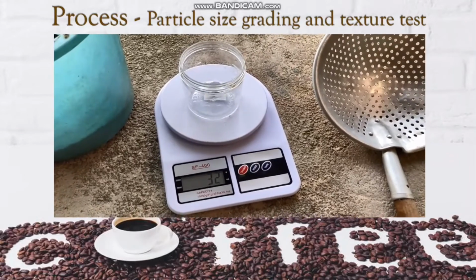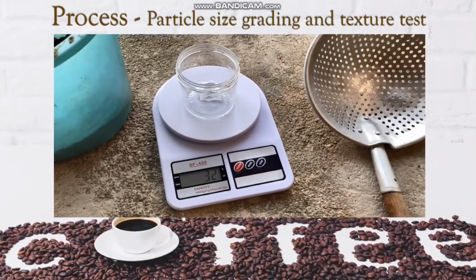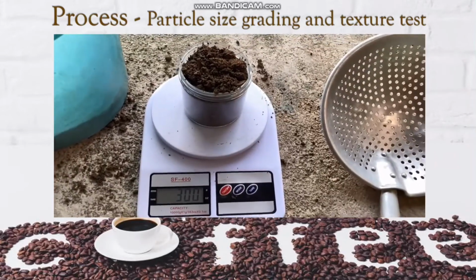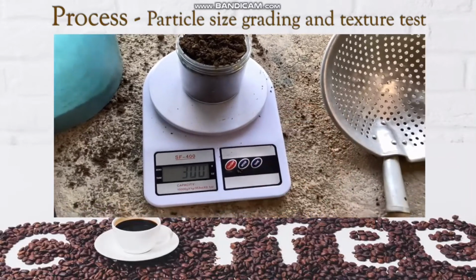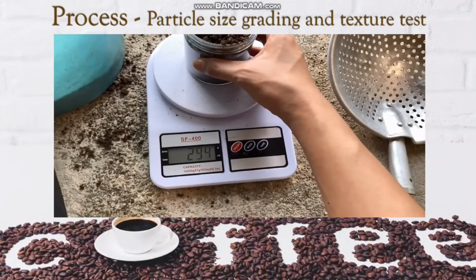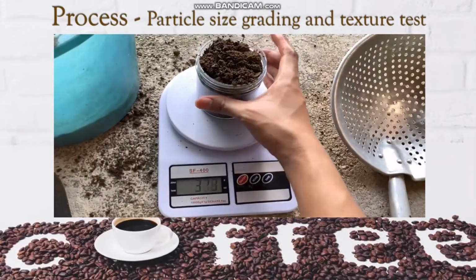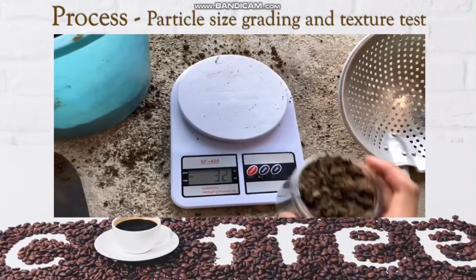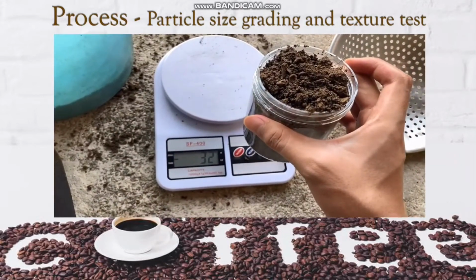So now we will add 300 grams of soil sample. Now we get 300 grams without the weight of the container, because I have turned the tare mode on. If I remove this soil sample, it will become negative 32, because that is the weight of the container without the lid.